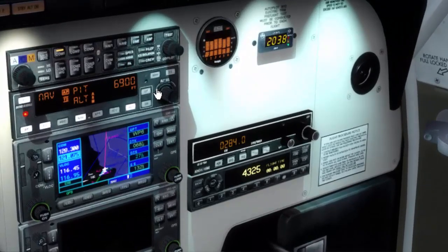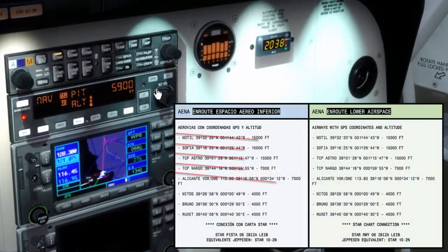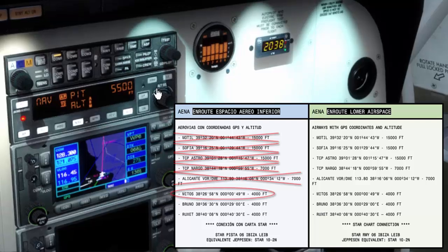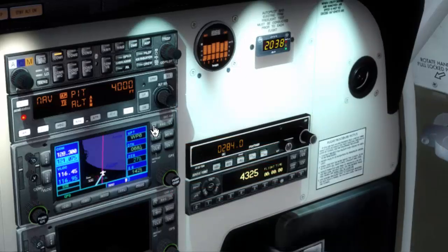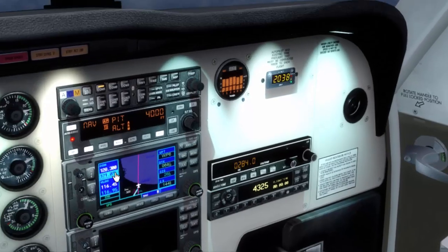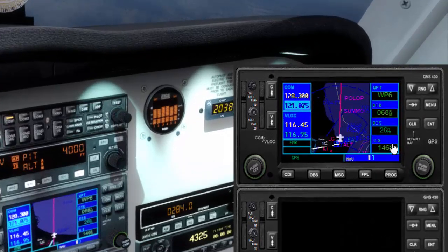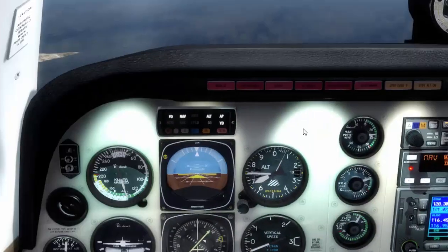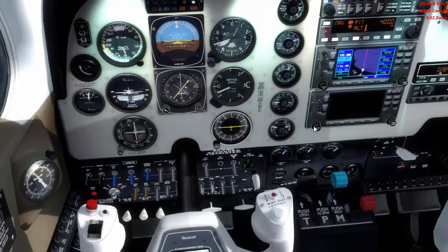Okay, I will take a look at the next point in our flight plan, and we again need to descend to 4,000 feet. And when we are descending to 4,000 feet, remember what will happen. The weight of our aircraft will push it forward to the ground, and the aircraft will tend to glide. So again, we will have to reduce the engine power by moving the black lever rearward, and by cutting also the RPM with the blue lever.